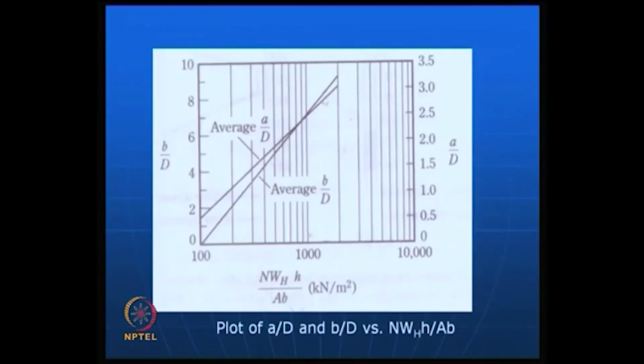There is an approach available in literature which can be useful in a design. We know the depth to be improved, so we should be able to know the number of blows required, the weight of the hammer required, the height of drop, and the area of cross section. If you have a 5 meter diameter, then pi by 4 into d square will give you the area of impact, and B is the depth. There is some relationship available in literature which has been quite useful.